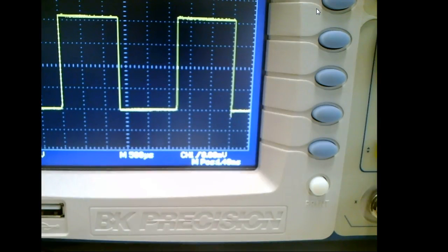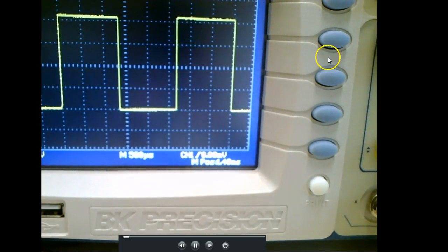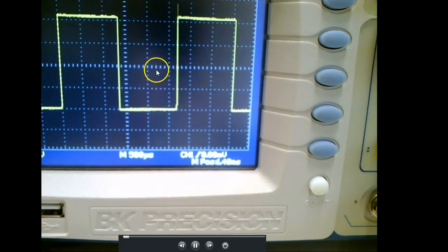It would be half of a division, right? Yeah, it is. It's 0.4. If this is a 1, then each one of these lines has to be worth a 0.2. 0.2, 0.4, 0.6, 0.8, and then that would be there. So now it's lined up. So that would be 5.4. Right? You understand that?